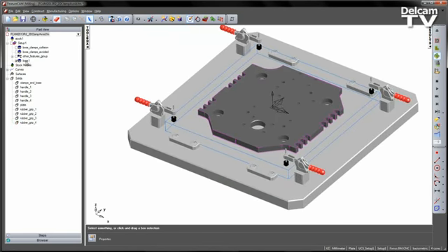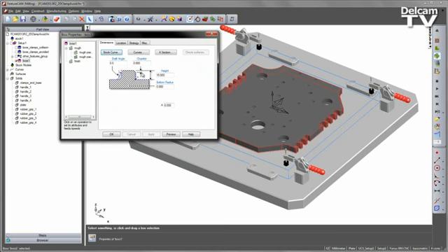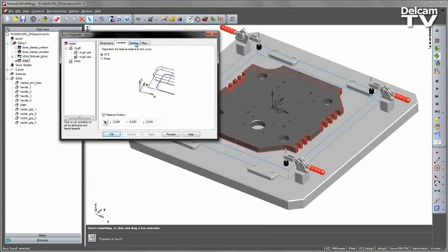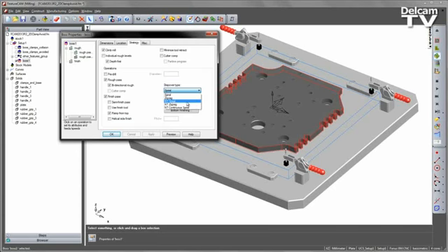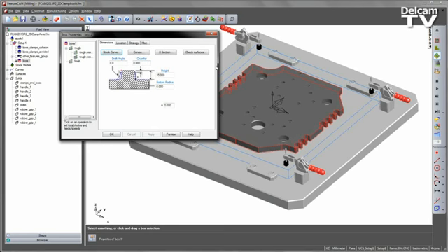Well, the first thing we need to do is in this boss I need to indicate the type of toolpath. You can see there's a new button at the side here that says Check Surfaces, and I want to use this option, but I need to change my toolpath strategy. So I'm going to do this by going to the Strategy tab and choosing NT Spiral. Let's select, go to the Dimensions area, and Check Surfaces is now available.